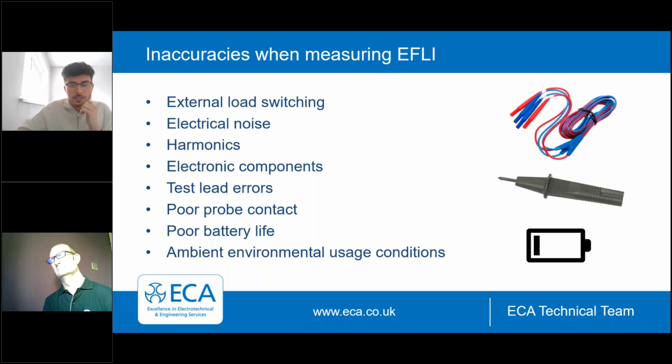And as well, the ambient environmental conditions that you are using the instrument in. Of course, when it's produced and checked, it's tested within certain parameters and certain temperature conditions. So if you're operating outside of that scope, or maybe at the lower and higher end of the scale, you may see some effects there. So there's some things to consider in terms of the accuracy and how it could be affected.